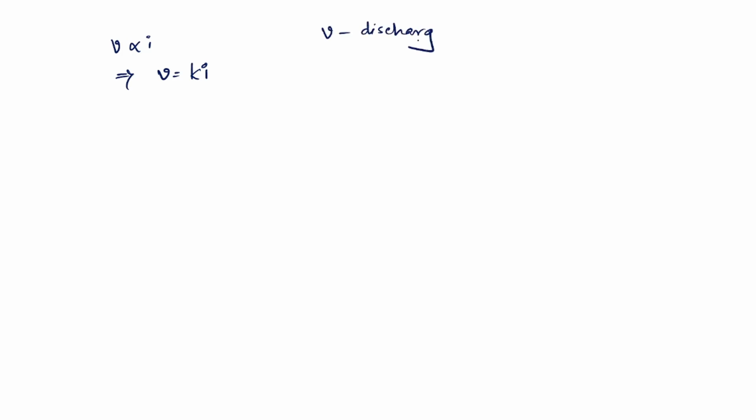First, according to Darcy's law, we know that laminar flow velocity is directly proportional to the hydraulic gradient, then v equal to k multiplied by I, where v is discharge velocity, it's not seepage velocity.